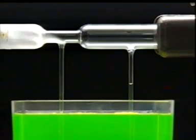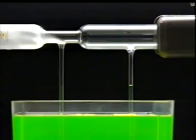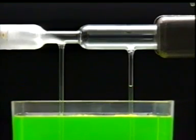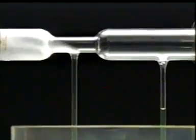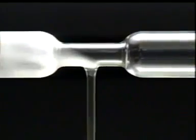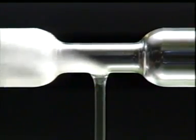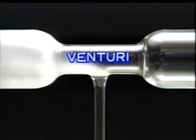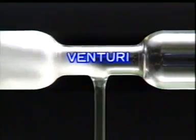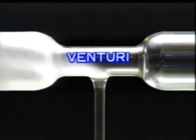At this point, the negative pressure is weak, and the water is drawn only part way up the tube. As the air enters the narrowed section, however, it moves faster. The negative pressure increases, so that more water is drawn up into the tube. The flow of air now turns the water into a spray. We call this kind of tube a Venturi tube, and the section where the tube is narrowed is the Venturi.